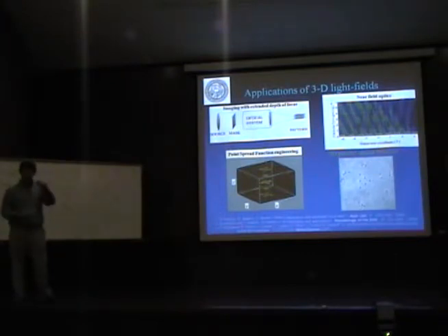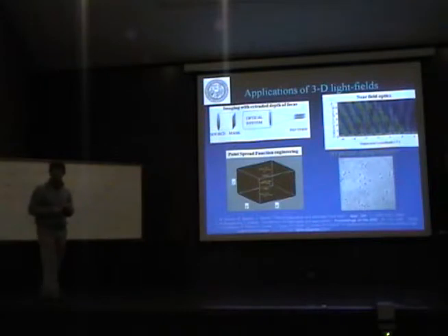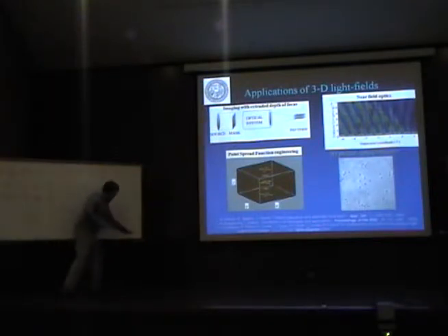The problem with that is normally you have a photoresist, which is thick. So if you try to get very fine detail in that photoresist, when the light hits the photoresist, it's going to expand. And then you cannot do a very small feature. Let me make a drawing here.